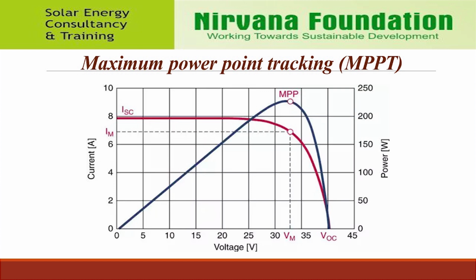Graph shows IV characteristics of MPPT charge controller system. MPPT checks output of PV module. Compares it to battery voltage. Then fixes what is the best power that PV module can produce to charge the battery and converts it to the best voltage to get maximum current into battery.